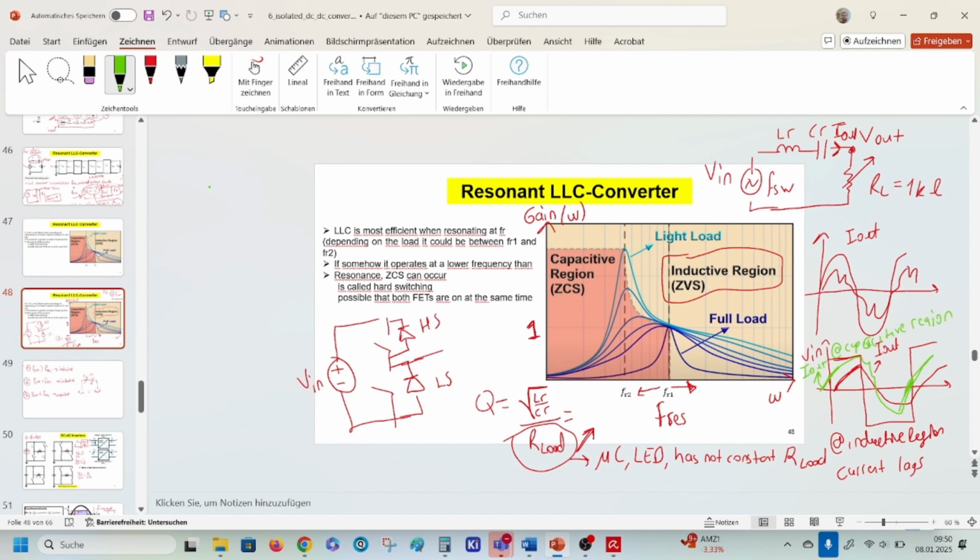And that would happen in zero current switching. The diodes, the two diodes, will be hard switched, and they will cause a lot of EMI problems and the efficiency will go down. For this reason, I want always to stay either equal or above my resonant frequency.